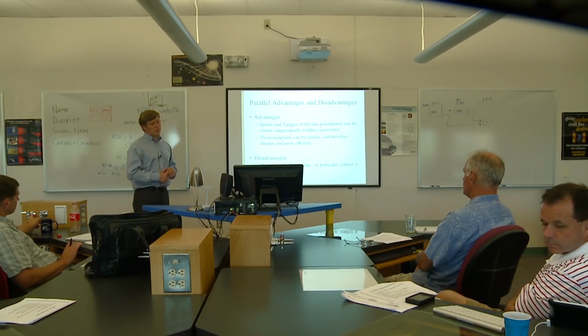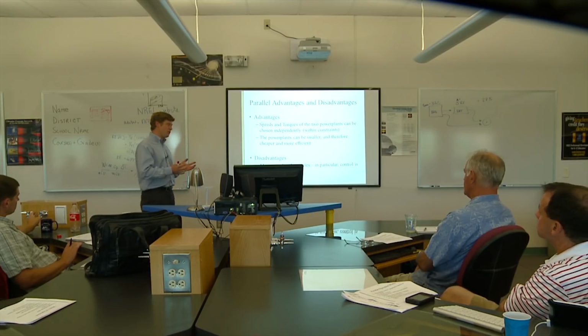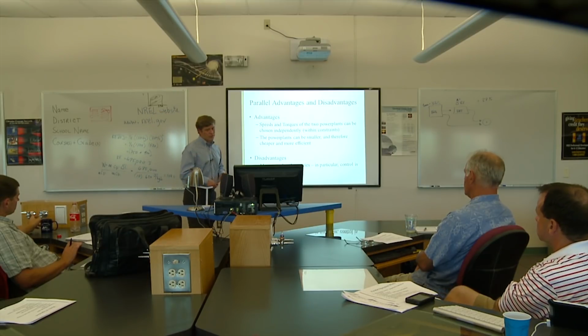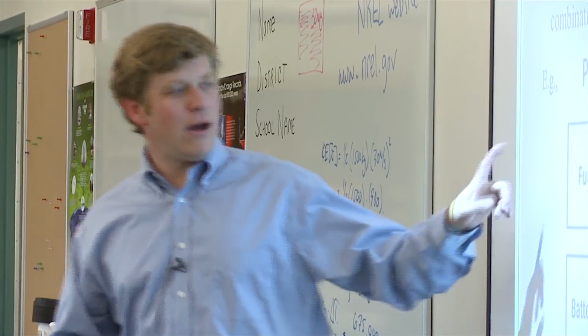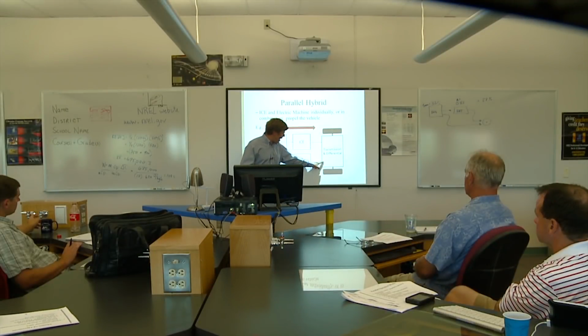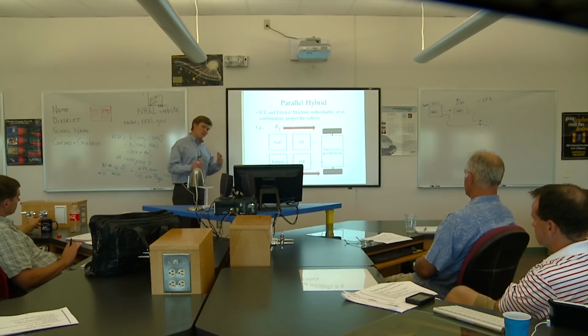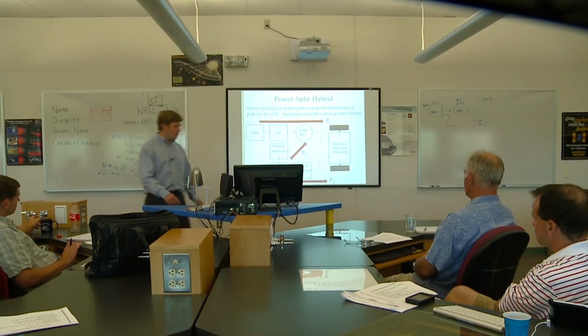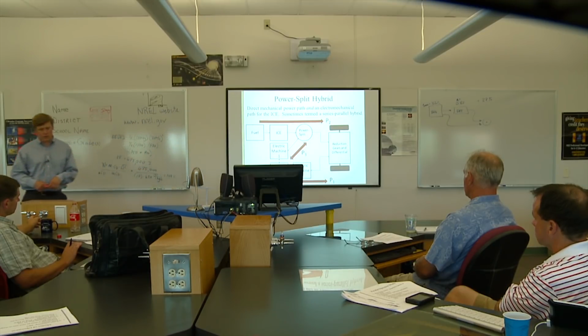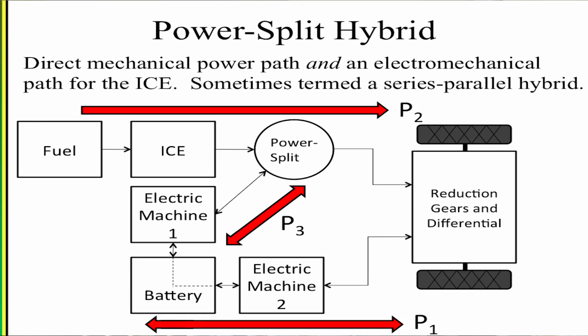You also have to do some stuff like, it's more difficult to do state of charge control, because what you end up doing is basically, instead of being able to directly charge the batteries, you have to run the engine and regen off of the same shaft, the same input shaft of the transmission. So there's some tricky stuff, but I think especially nowadays it's possible to do that, and that we can get around those things. And so you can take advantage of those efficiency advantages.